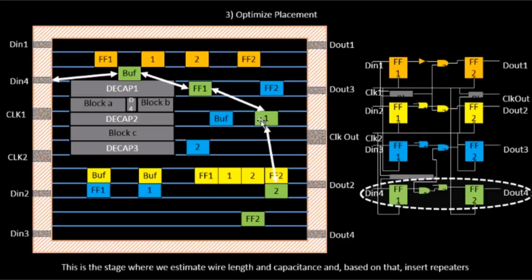Next we have this connection from this point to this point. Again, the distance is a bit high, and there is also a logic which is sitting over here, and this is again a normal condition. The way the routing might happen is that the internal routes of flip-flop 2 might be in some layer, let's say metal 1, metal 2, and the signal connection from 1 to 2 will be on a separate layer, like metal 3 or something of that sort.